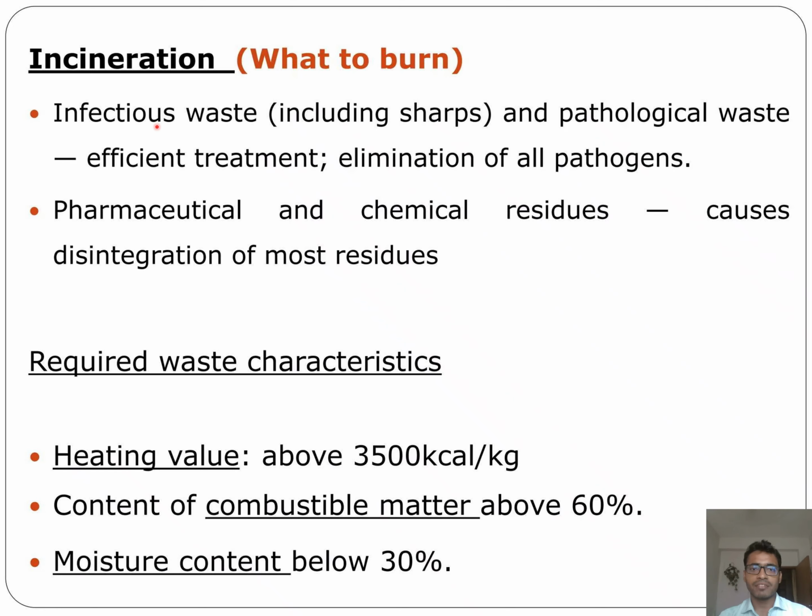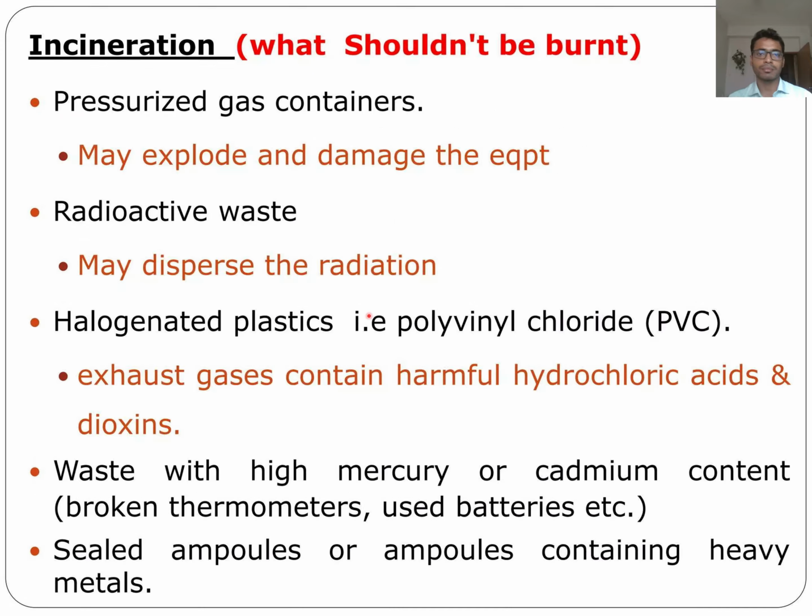So what to burn? Infectious waste, pathological waste, pharmaceutical and chemical waste. Okay. And the required waste characteristics are: heating value above 350 kilocalorie per kg, content of combustible matter above 60%, and moisture content below 30%.